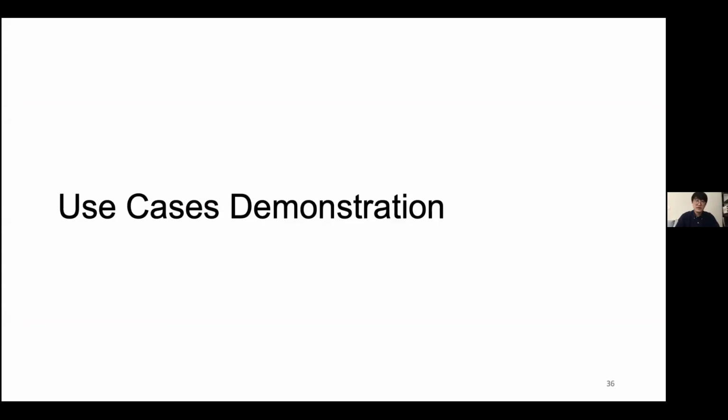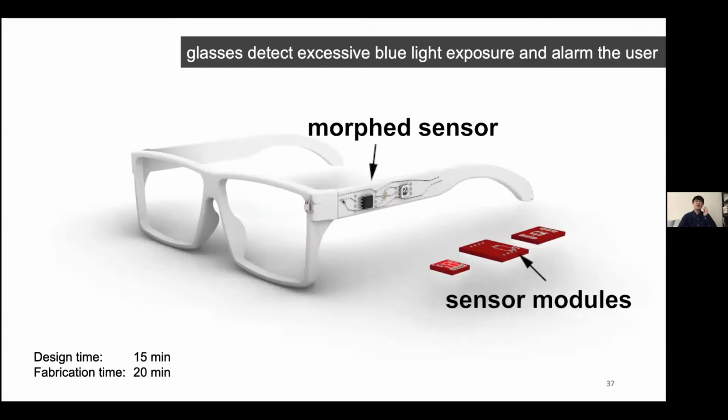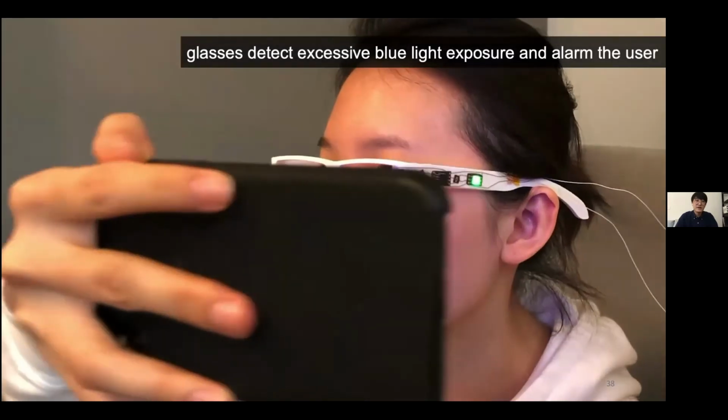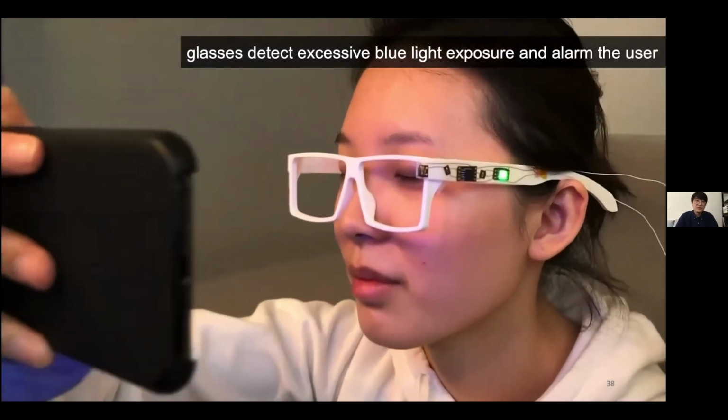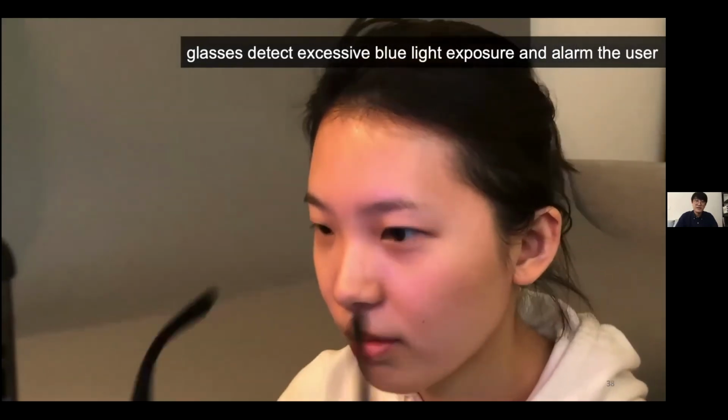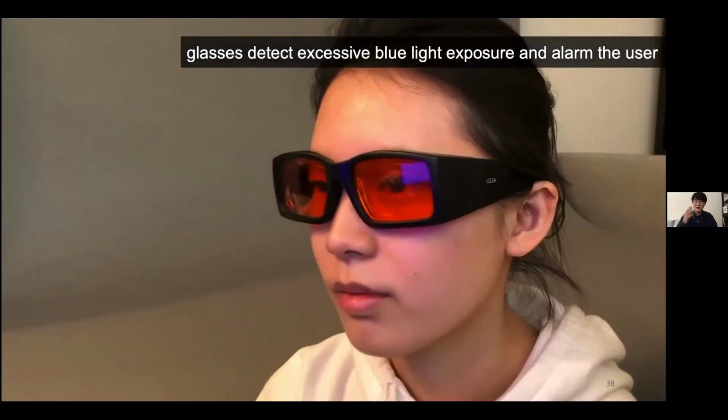We used Morph Sensor to prototype a range of interactive devices, highlighting different levels of complexity. Let me show you some of them. This is a glasses design that detects excessive blue light exposure and alarms the user. It is achieved through a blue light sensor plus the microcontroller and the display LED, so that your eyes are always protected.